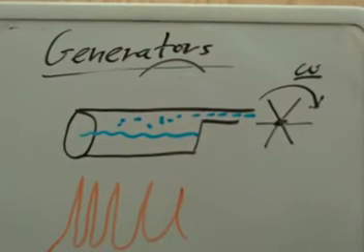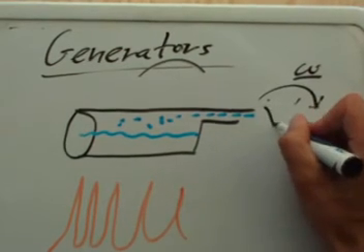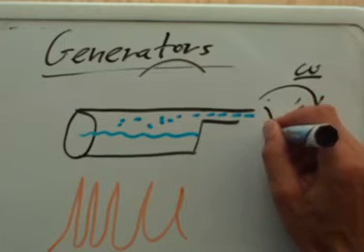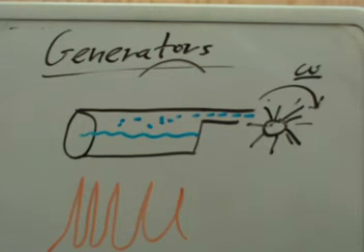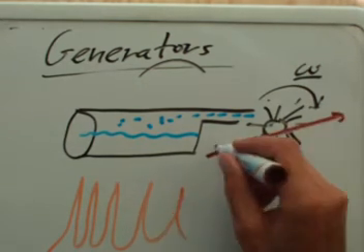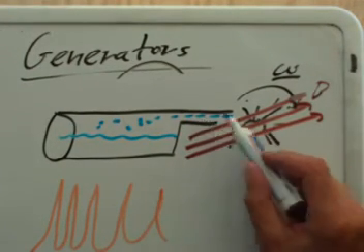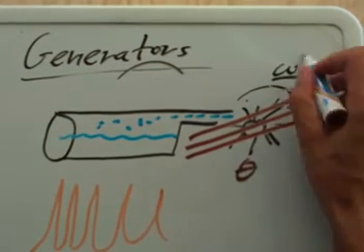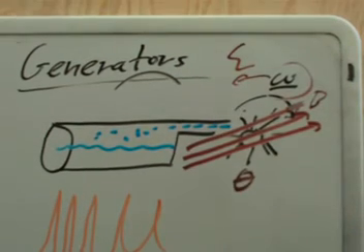And this turning here is your omega. This paddle wheel turning is the omega, because what you could do instead of drawing, well, you can leave the paddle wheel like that, but let me draw it a slightly different way. You're going to need the paddles on there so the steam molecules can hit them, but maybe in the interior here is where I'll draw the loop, so the loop can start to spin, and as the loop spins, we can immerse the entire thing in a magnetic field. Again, I'm losing the perspective with the two-dimensional drawing here, but maybe I'll immerse the entire paddle wheel in a magnetic field. And if I can engineer some way of getting this loop that's being spun by the steam to change its theta in terms of that omega in Faraday's law, then as long as I have the fire, as long as I have the steam, as long as this paddle wheel turns, this omega here will give me my induced EMF, my voltage out.